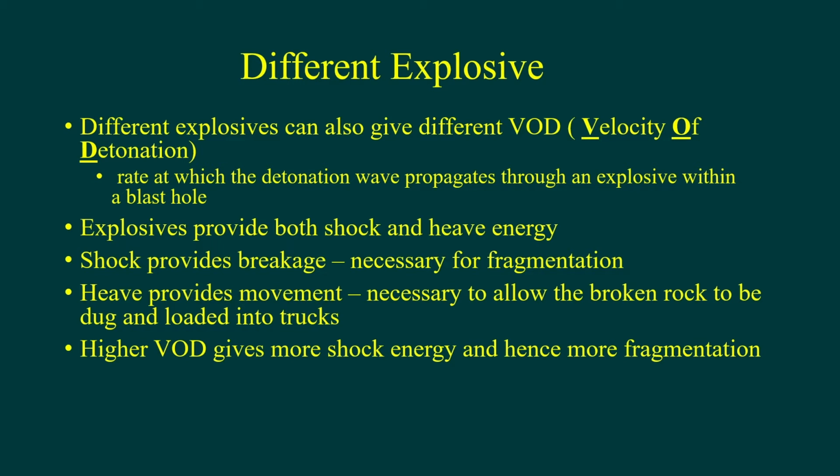So if you follow that logic, if you have a higher VOD, you will get more of the energy going into fragmentation. But you need to remember, you also will have less energy going into heave, and that could have implications with respect to the ease or lack of ease with which that broken rock can be subsequently dug. So there is always a compromise having to be made there.